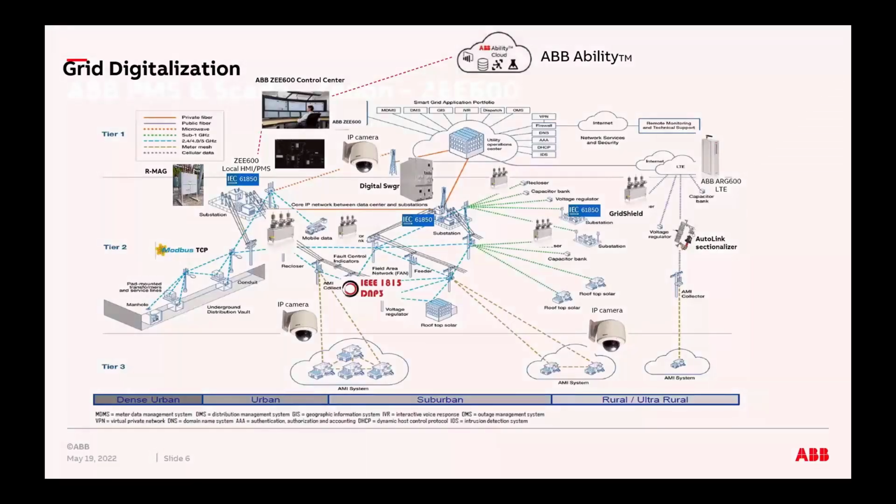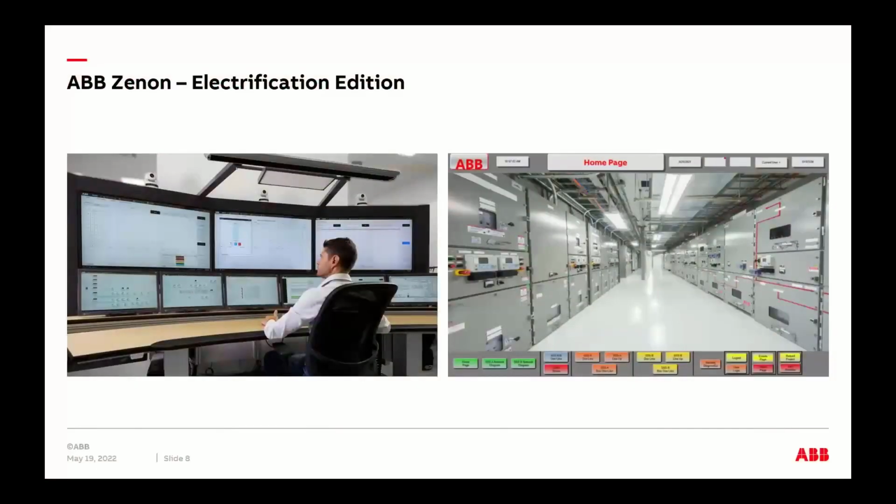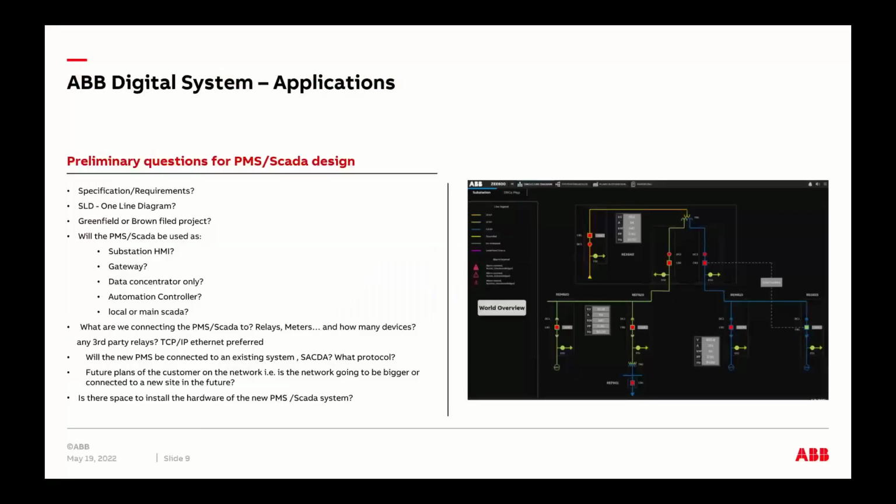So now let's move to this interesting topic. So once I did all that, let's say all this digitalization, right? I put all my hardware there. Everything is brand new. All digitalized. I have digitalized meters, digitalized protection, digitalized communication. I have fancy switches. Like I said, typically they are the high end that will support 61850, for example, if you're using the 61850 standard. Maybe you're doing redundancy of communication, maybe PRP, HSR. So those are special switches. And I will show you in the following slides how it looks when they're all implemented together.